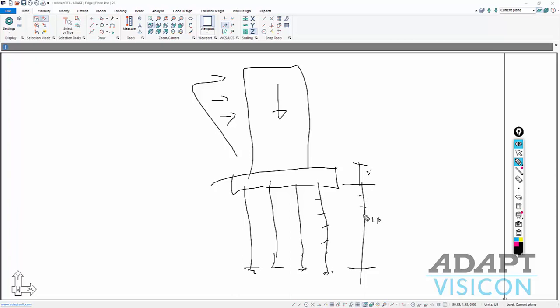So we're going to break this into increments of 5 feet. And at each increment, we're going to add a spring, a lateral spring. So you're going to have a KXX and a KYY subgrade modulus value for all of these piles. And we're going to then run the model globally with the inclusion of the springs to evaluate the overall behavior of the system. So this is roughly what we want to model.